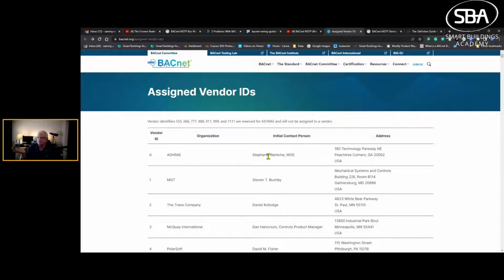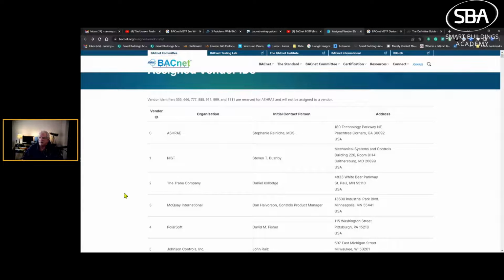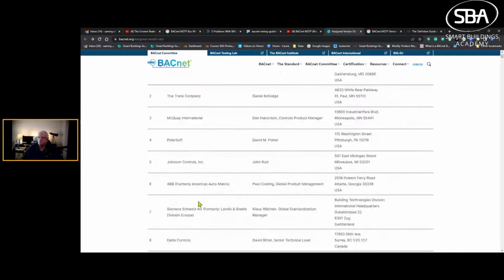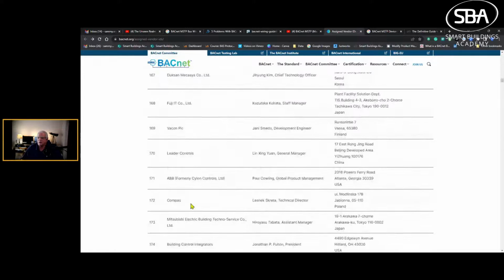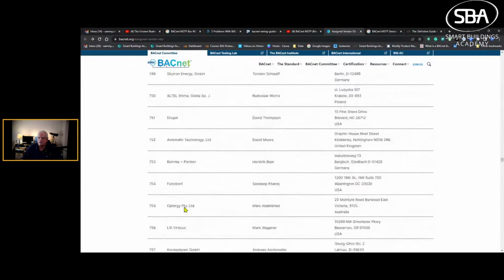0 is ASHRAE itself, and ASHRAE is the industry standard for defining BACnet. ASHRAE 135 defines how BACnet operates. Vendor ID 1 is the National Institute of Standards. ID 2 is the Trane Corporation. 3 is McQuay. 4 is PolarSoft. So it goes on. Johnson Controls is 5. ABB is 6. It goes on down, and there are just thousands of vendor identifications.